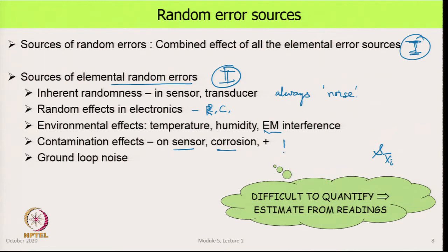This is a little tricky issue in the practical world, where there are many instruments where cleaning and keeping it clean is a major challenge. The errors are not insignificant, and if you do not regularly remove the contamination, the measurements would be quite seriously off.